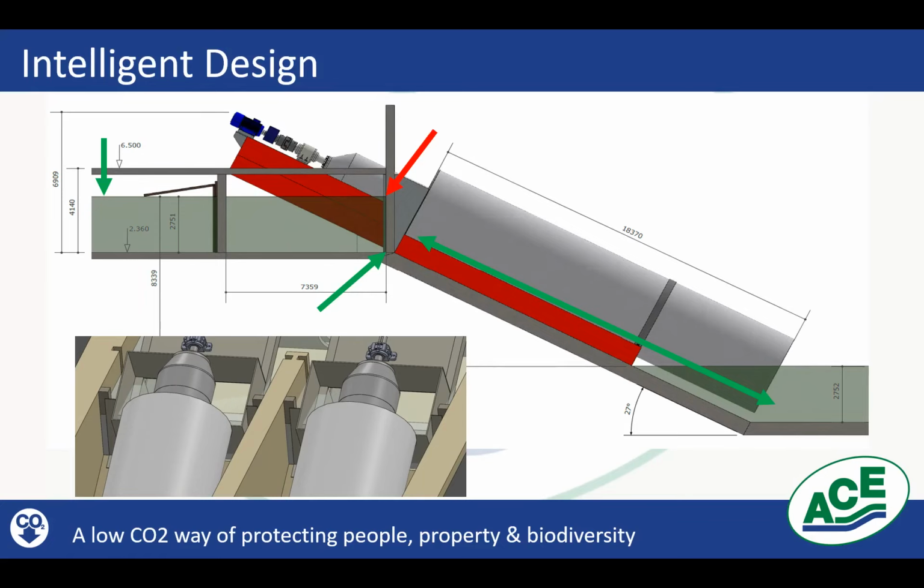That's not just reducing the effective lift, therefore reducing the energy consumption. If this was a tidal pumping station, the overspill solution where you'd have a traditional screw tipping at the red arrow, of course, you're effectively pumping 2.7 meters extra height than you actually need to, so using a huge amount more energy than what you actually would need to.